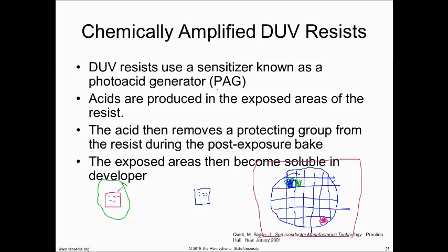Then I'm going to use what they call a reticle. It's no longer a mask. We're going to give it a different name. And then I'm going to go to the next one and do this one perfectly. And then I'm going to step to the next one, step and repeat, and go to this one and do it perfectly. Then I'm going to go to this one and do it. That's what we call a step and repeat.